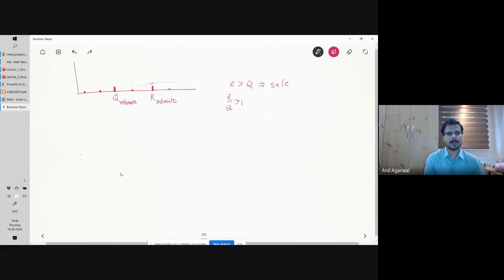And if I test large enough number of such columns, study the behavior of large enough number of such columns, this is frequency. Okay, if I study the behavior of large enough numbers, then I can draw it as a frequency versus measured values plot. Okay, so if on the vertical axis I'm plotting the frequency, so maybe out of 100, some 20 will be within plus minus 5% of this value, and then some 15 will be plus minus 10% of that value, and so on. And that's how this actual distribution will be.